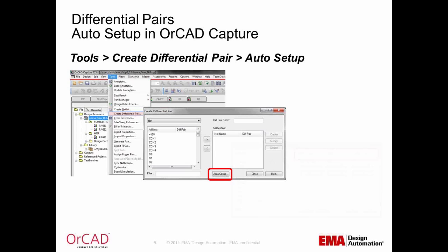You will need to check your allegro.cfg file to make sure all properties in your design will be passed to PCB Editor. To do this, click on the Setup button and then on the Edit button in the Setup form and add any missing properties to the list.